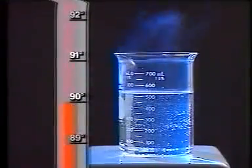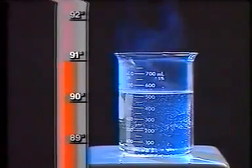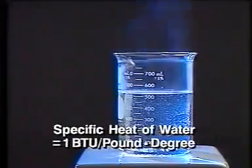When we measure heat, we use BTU, which stands for British Thermal Unit. 1 BTU represents the amount of heat necessary to raise the temperature of 1 pound of water 1 degree Fahrenheit. Many materials require less heat to change temperature. The property that represents this heat requirement is called specific heat. The unit for specific heat is BTU per pound degree Fahrenheit. The specific heat of water is 1 BTU per pound for every degree.